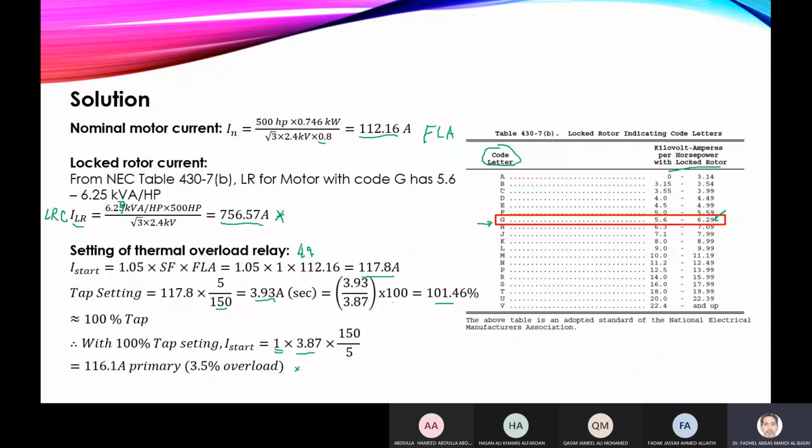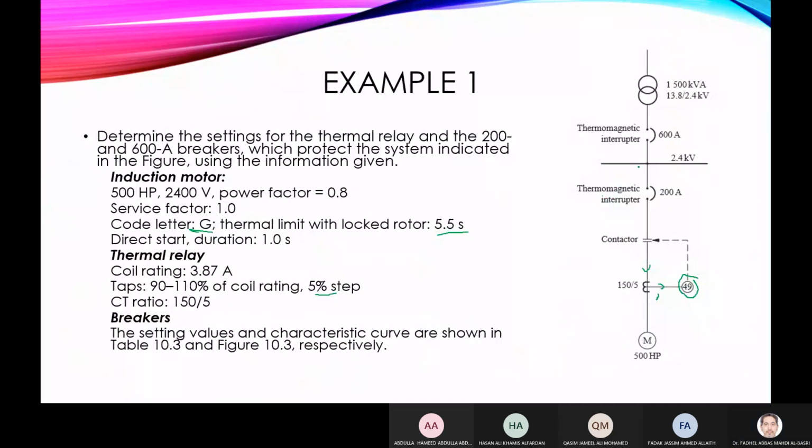Now setting the breaker, which is at the top, this one. So what does this show? This will give me thermal overload protection at moderate overload conditions, but I want to provide another protection here. We provide for short circuit for when the rotor is locked. I can trip with this one and so forth, and short circuit also protection.